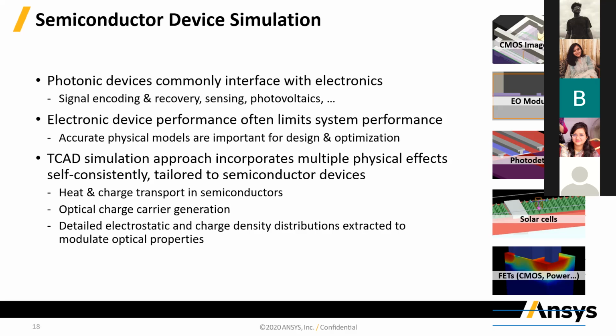The TCAD simulation approach allows you to incorporate these multiple physical effects self-consistently for these semiconductor devices. Now, the heat and charge transport in semiconductors, this is what we are trying to capture with our charge and heat solver. Some of the other effects that we can capture is, for example, optical charge carrier generation.